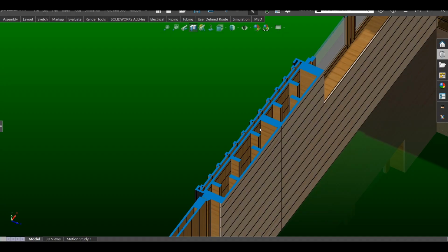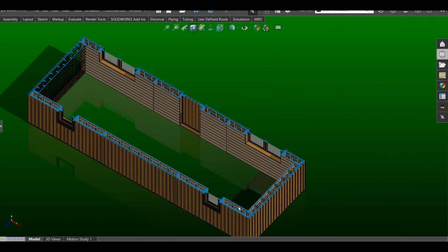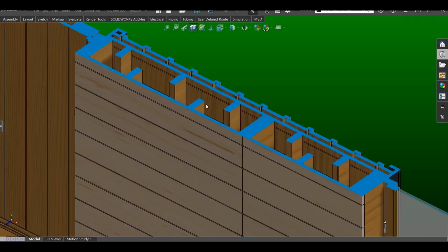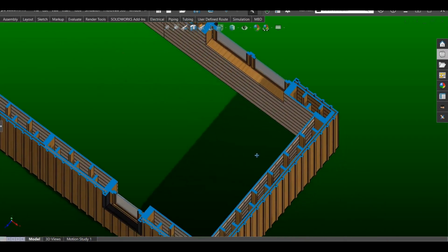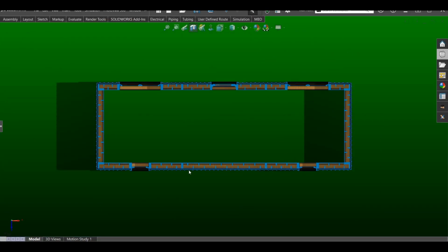Like you glue and stick 2x8s on each other, and it's basically like a 4x8. And you got 8 and 6 here, and it acts like big inner pillars, and they also block the air, so it's better for fire, and for a spot like the siding here where there's no window, this is where it pays. And even here, you can see that you have that huge section of insulation, no thermal bridging.